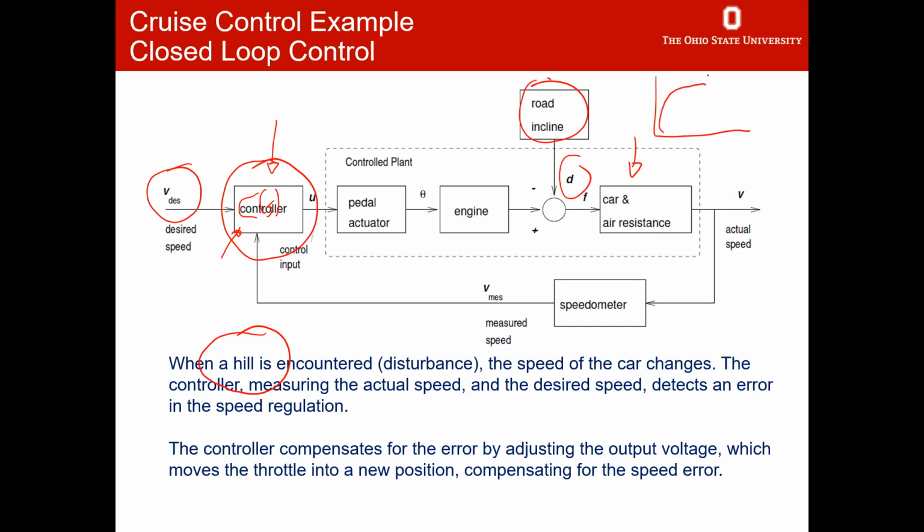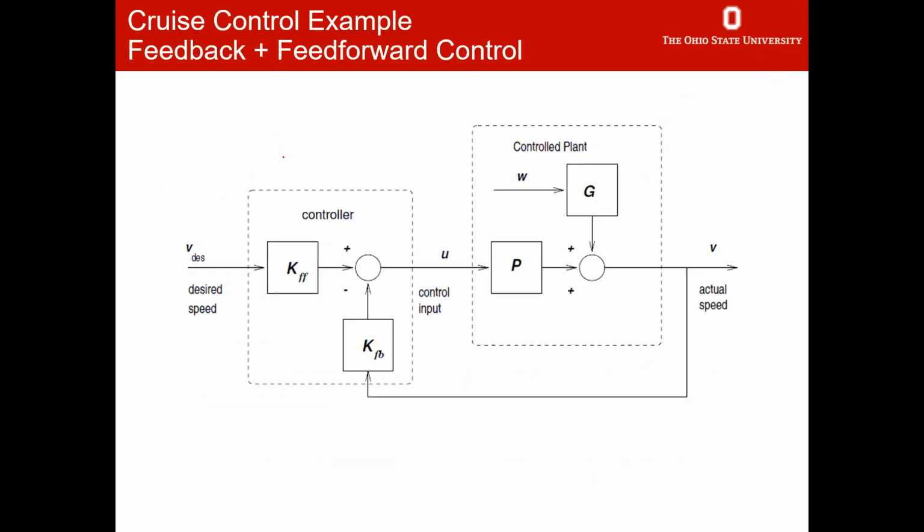You will reach a desired speed, then I will change the road slope, and this is my desired speed. Speed is going to go down and come back. So the properties of what happened here have to do with how well you design your controller right here, okay? To make this a pleasant experience for the driver, we gave authority to the automatic system.